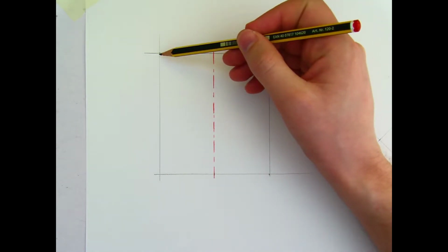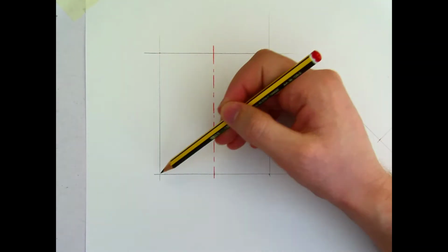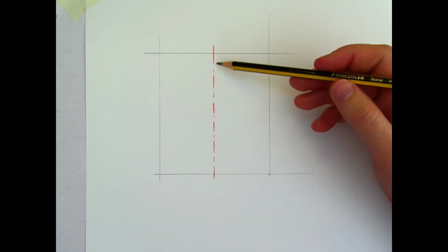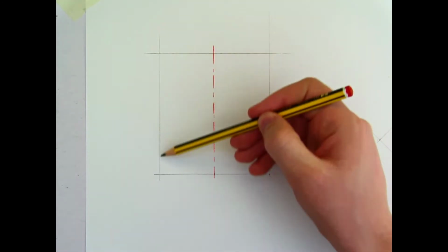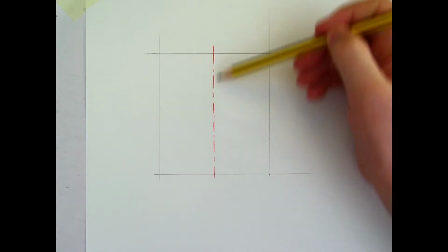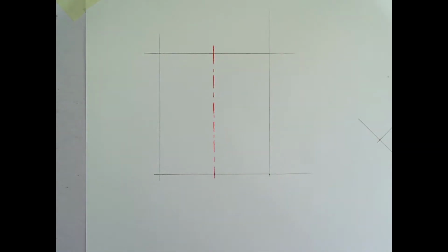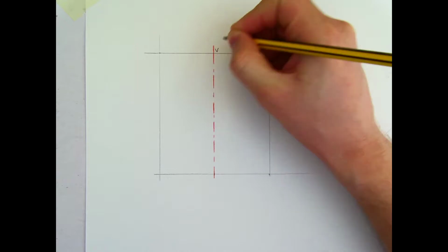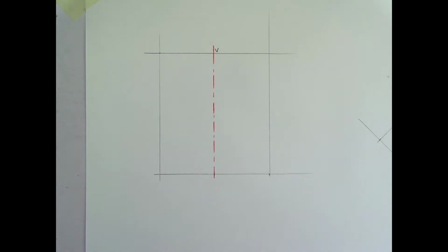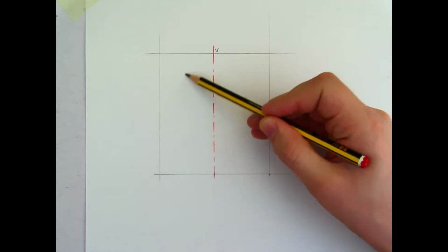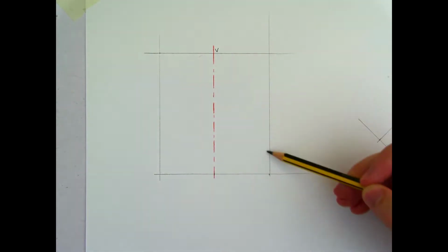This rectangle is 100 tall and it is 90 wide, and this is my axis splitting the center of the rectangle. The axis is then halfway, 45 millimeters. So we are going to draw a parabola, and I want my vertex, the top of the parabola, to be up here at V, at the very top. So what I need to do is draw my curve. My curve is going to go up along this way somewhere, coming across the top and back down here on the opposite side.